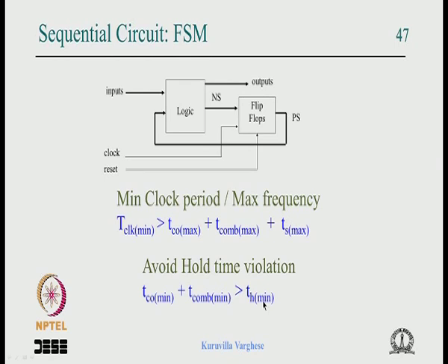So why are we worried about metastability? The question is that in a data path and in an FSM we take care of the destination register setup time and hold time. That is an essential part of the timing design.